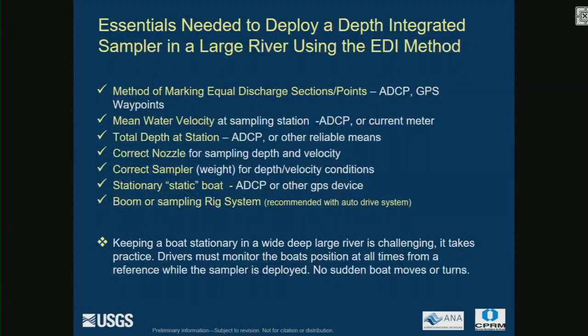It's very intense, especially in flood conditions when we're looking at 3.5, 4 meters per second, and we're lowering a 300-pound sampler off that size boat. Both motors are running, and they're probably at half speed. And that D99 is going to have probably about a 10-degree drift angle on it, even with that type of weight, at probably 90 to 100 feet.